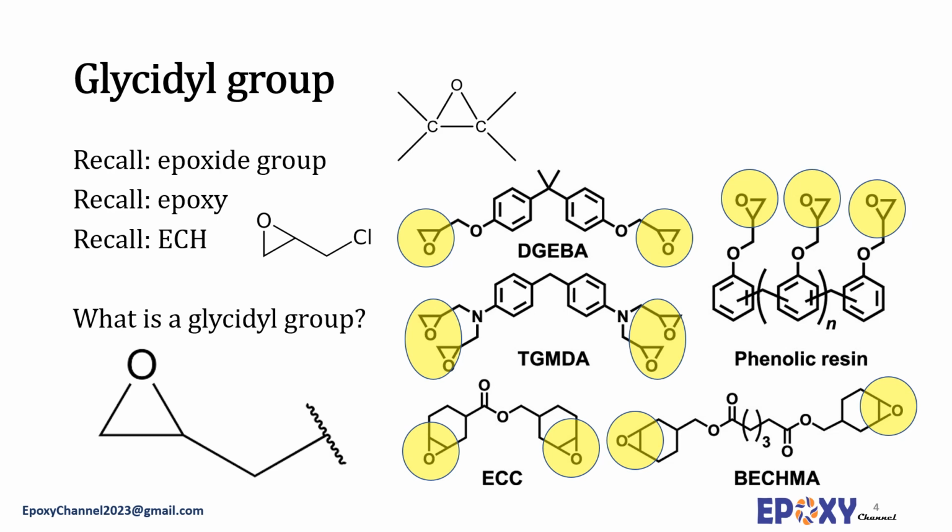If we have two glycidyl groups in the structure, it is called diglycidyl epoxy resin. If we have four of them, then it is called a tetraglycidyl epoxy resin. There are also cases in which we have a structure with epoxy resins where glycidyl groups are not present. These types of epoxies are called non-glycidyl epoxy resins. In the presented schematic here, the bottom two epoxy resins are not glycidyl epoxy resins. Often non-glycidyl epoxy resins are divided into cycloaliphatic and aliphatic epoxies.